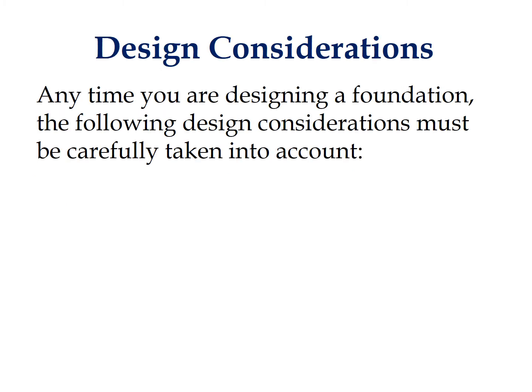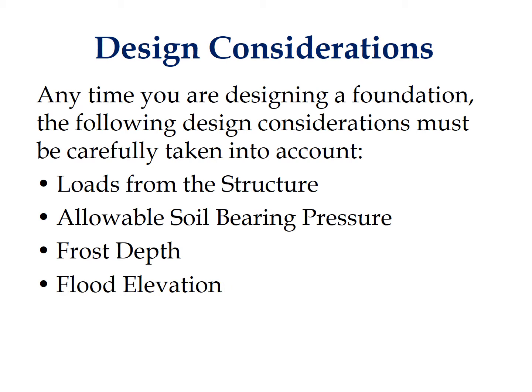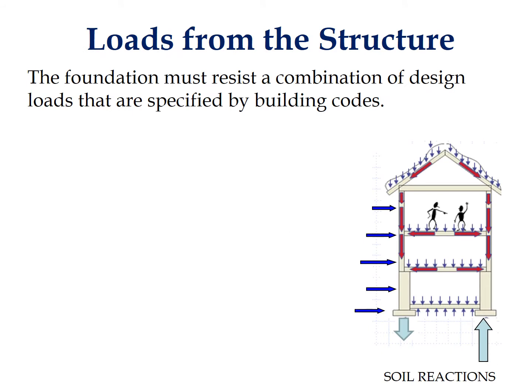Anytime you are designing a foundation, the following design considerations must be carefully taken into account: loads from the structure, allowable soil bearing pressure, frost depth, flood elevation, drainage, and cost. The foundation must resist a combination of design loads that are specified by building codes.